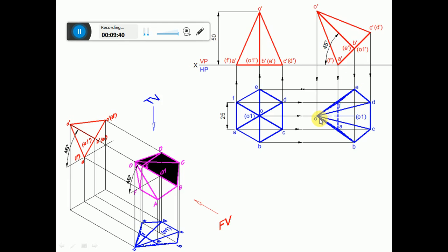So all the exterior edges of the boundaries of the solids are visible. So this is the first condition of visibility. So you dark them: OB, BC, CD, DE and OE all are on the boundary. So you dark them with dark lines.